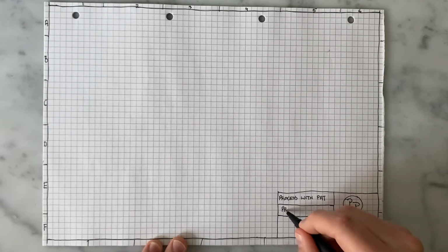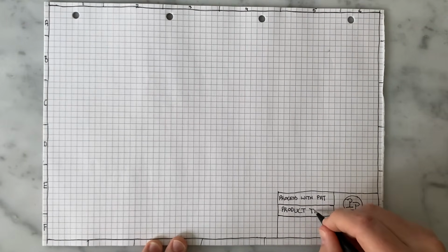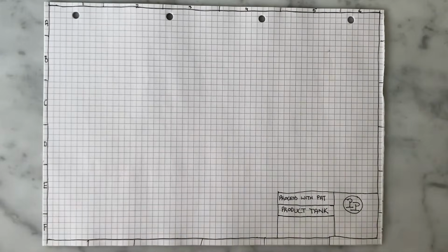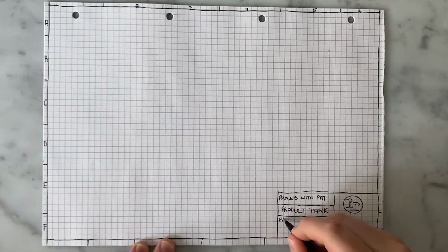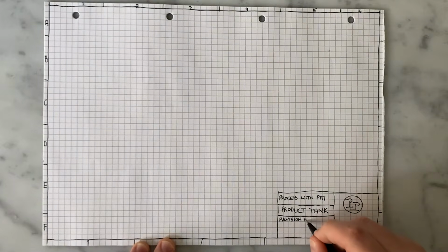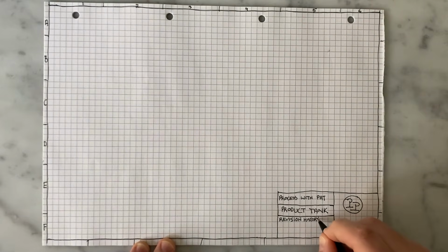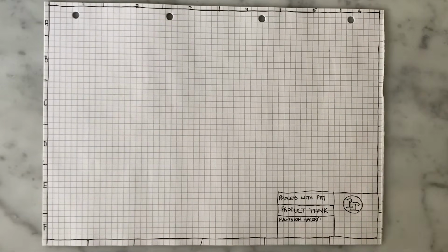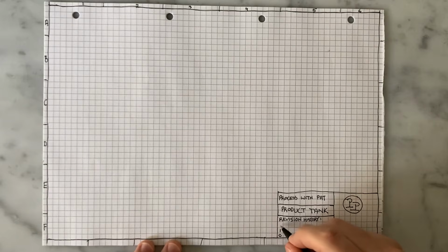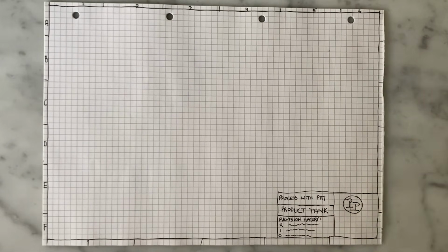Next, you need the name of the drawing, so what is it that we're showing on this drawing, as well as a revision history. The revision history contains small details about what's changed in various revisions of this drawing. So you'll find things like first issue, issued for design, approved for construction, as built, meaning, okay, we've designed the thing and built it, but is the thing that we installed even reflective of what's on the plant itself? If not, we should update the drawing.